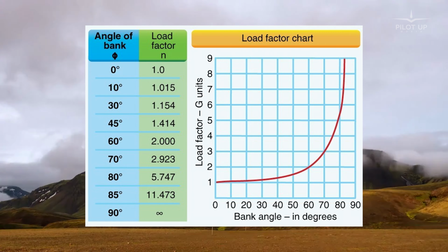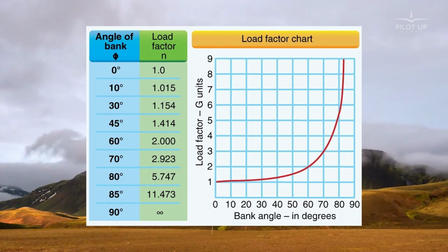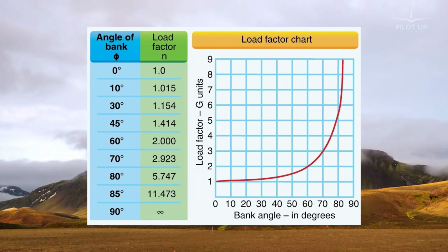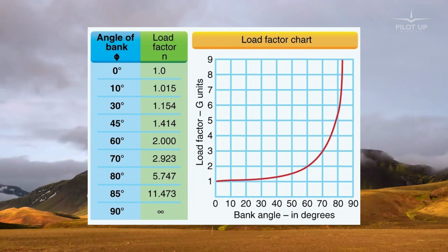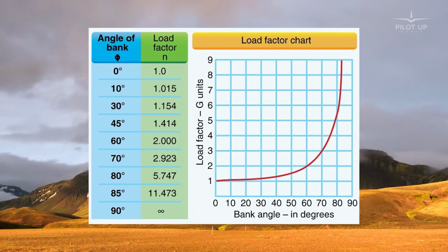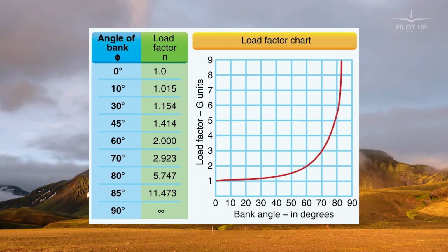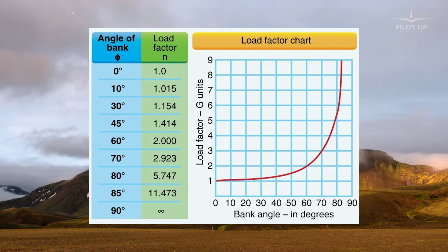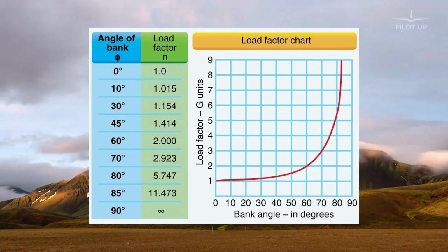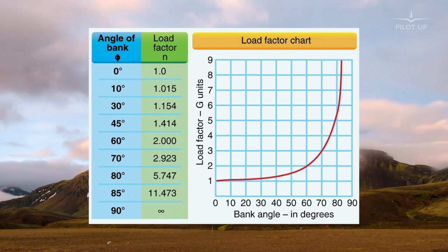If we look at the load factor for each bank angle we previously discussed, we can see that the bank angle of up to 75 degrees still falls within the safety envelope tested and certified for the Cessna 152, but the force will already be at 4 Gs. But why does a simple turn increase the G-force of an aircraft so much? In fact, the turn itself does not increase the G-force to these levels.